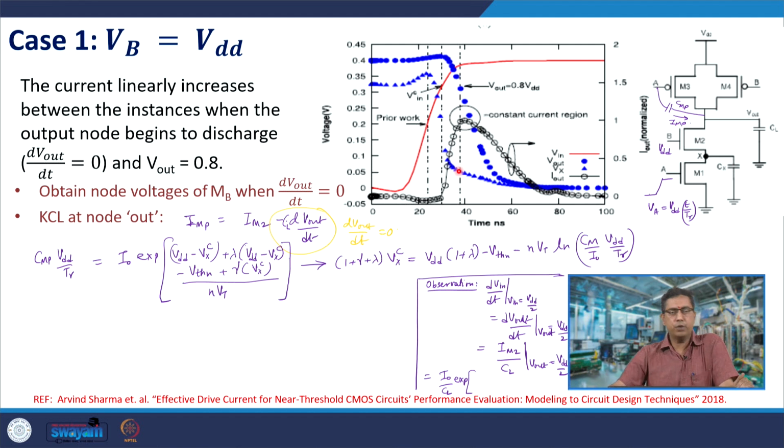It may change from 0.1 VDD to say 0.08 VDD or 0.12 VDD depending on the PDK, but it would be a fixed value for every PDK irrespective of the fan out load, for the balanced stage effort case. That is, the input and output transition times are almost equal.